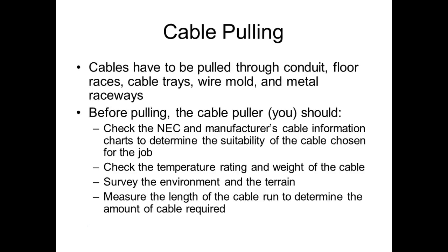So the act of running the cable through conduit, or even in a cable trough, we refer to this as pulling. That's just the name. So even if you're laying it in a cable trough, we still call it pulling. Cable has to be pulled through conduit. So you're not supposed to run the cable through the conduit while you're installing the conduit. You understand that? You're supposed to install the conduit first, right? And then do what? Then pull the cable through there.